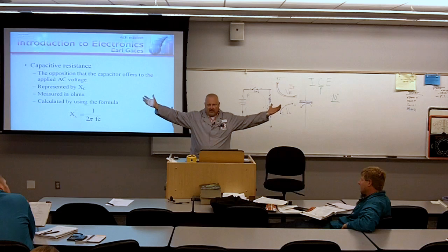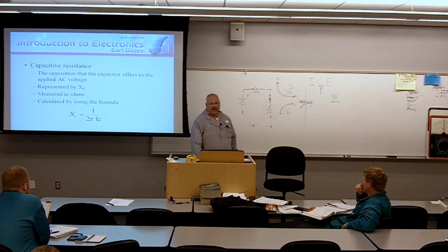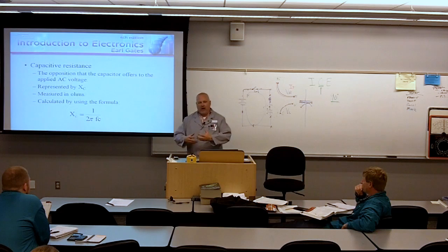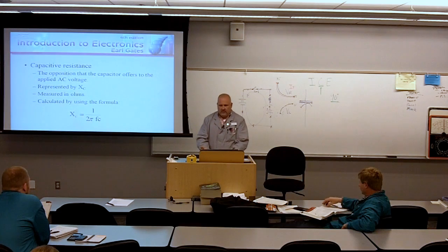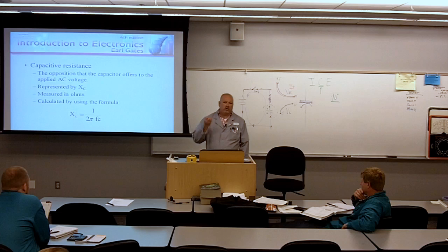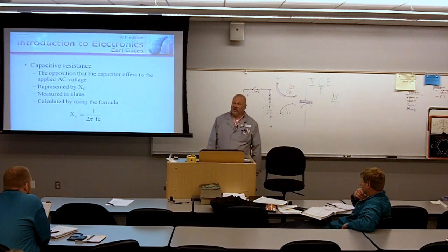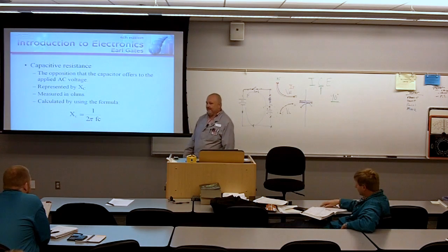If you apply this formula to an AC capacitor in a circuit like this, it's going to show you how many ohms of reactance it has. And then you can use the same math that you used at the beginning of the quarter analyzing those simple series circuits that I gave you to analyze. The exact same thing. So quite frankly, this whole lecture is a waste of time.